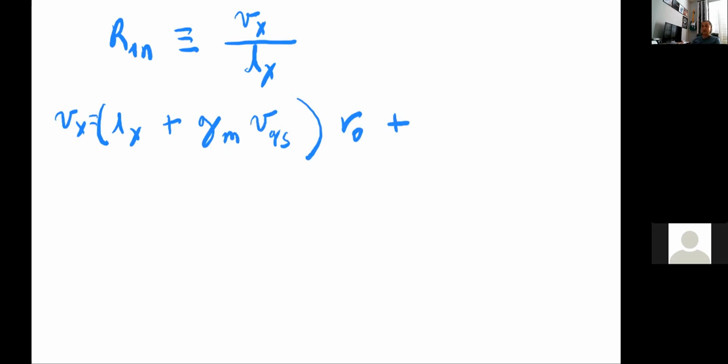And then another part of that voltage on that other end is the voltage across the load. So that is that same current, because remember that all the current that goes into the source of the common gate is seen at the drain. And then that current is going through the load. So the voltage at that other node, at the drain of the common gate, is that current times the load. Okay.